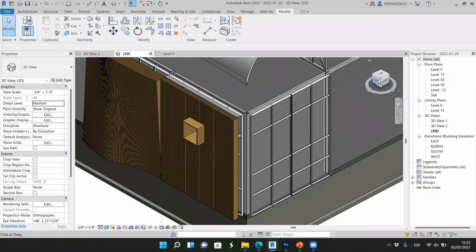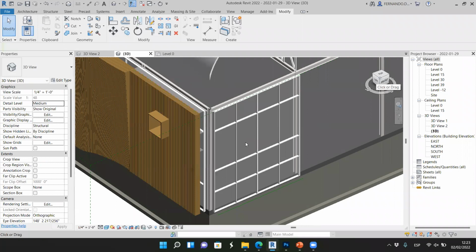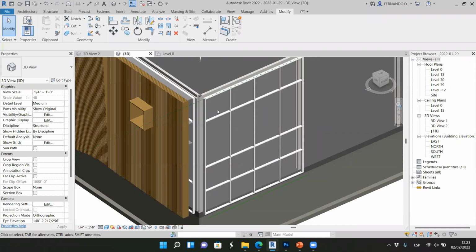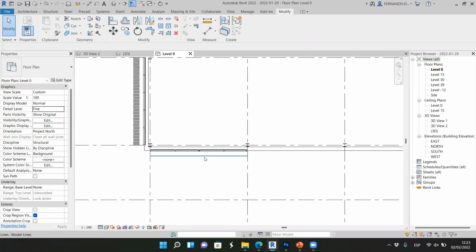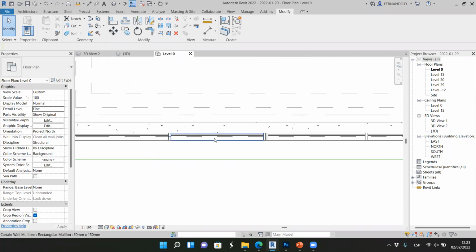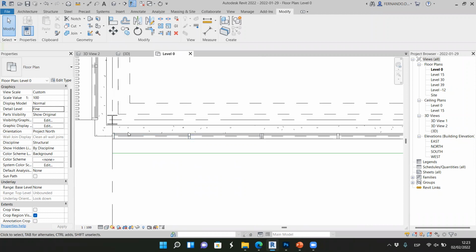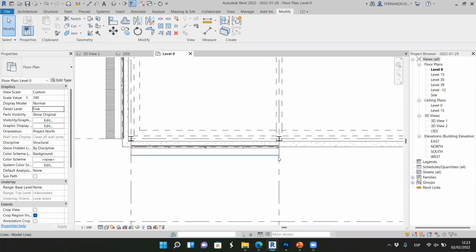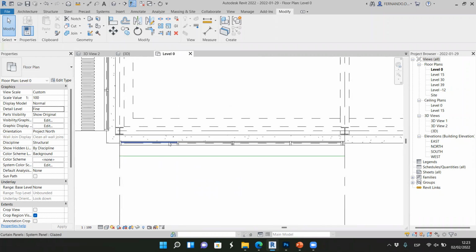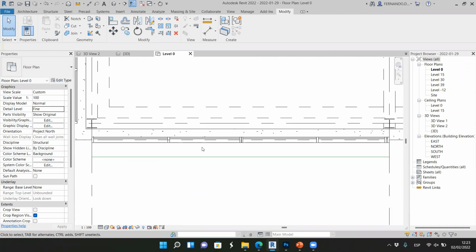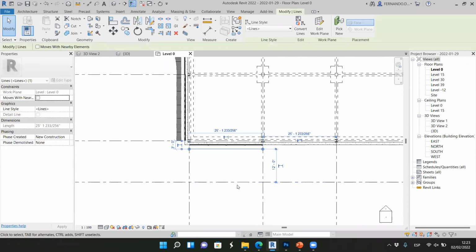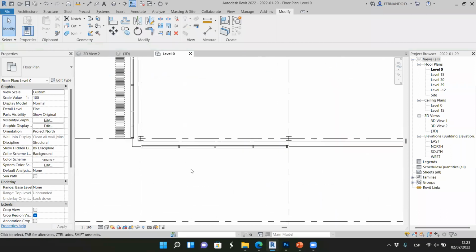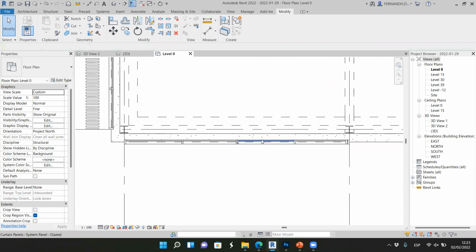I have created a wall here. You see, this is a curtain wall. It's in the southern facade, so I'm working on this corner, and I have just created this curtain wall here, and now I'm going to create a double skin facade between this wall. Well, I need another line, and I need this buffer space here, and this is what I'm going to do. Well, I have this line here. I'm going to do it again because I want to have a reference. Okay, so this is the original curtain wall, but I want another line here. Imagine that we have like 3 feet.